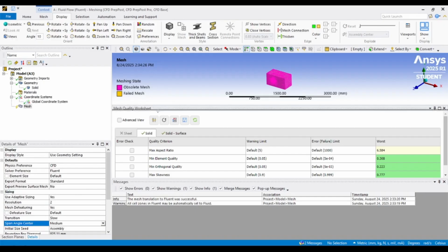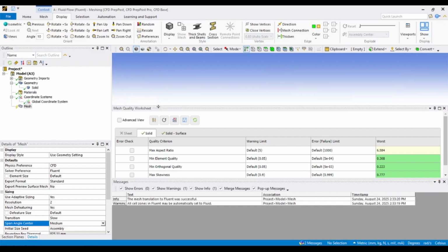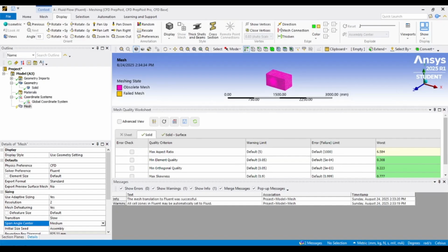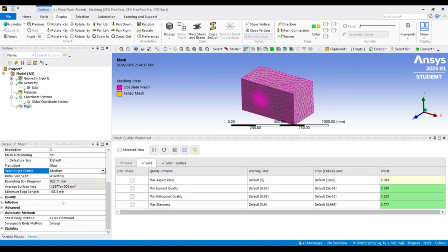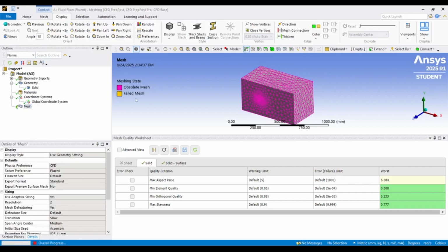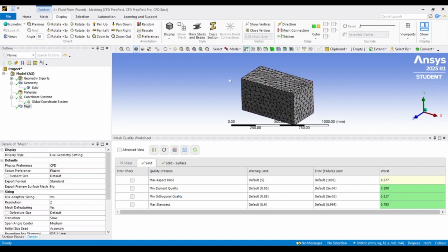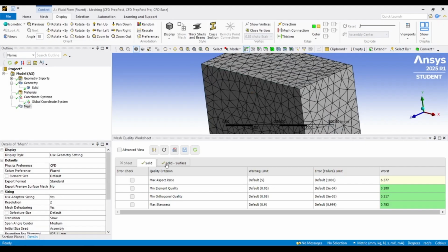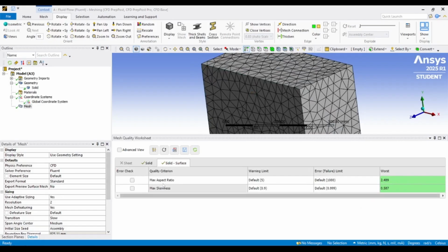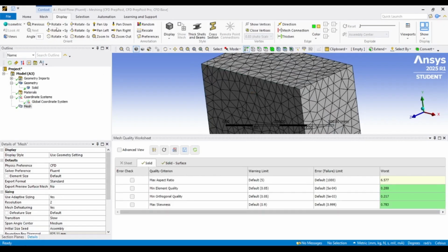To visualize this, go to the Animations panel and create an animation for velocity magnitude or vorticity contours. Setting around 100 to 200 frames evenly spaced in time gives a smooth playback, showing the periodic nature of the flow. You can export the animation as a video file directly from Fluent to include it in reports or presentations.